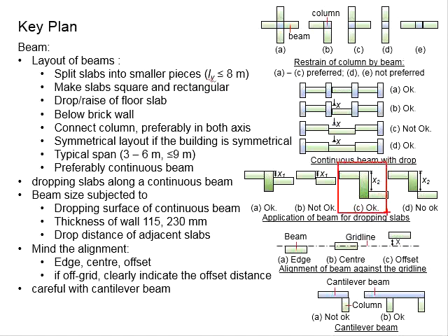This should be the right design, and this design is going to fail. There is no direct connection between the beam and the adjacent slab. Normally we will put the soffit of the beam at the same level as the soffit of the slab.